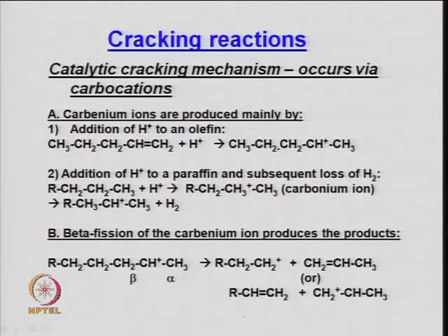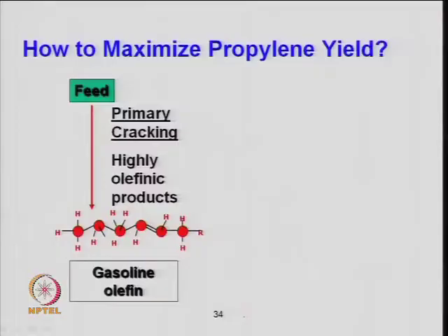Similarly, in the cracking reaction, larger molecular weight compounds are cracked into smaller ones, and again zeolite or silica alumina type catalysts are used in this process. Propylene is nowadays in refinery petrochemical integration, and a high yield of propylene is desired. So how do we improve the propylene yield? Selective catalysts are required which can maximize the olefins, especially propylene, generally for petrochemical purposes.